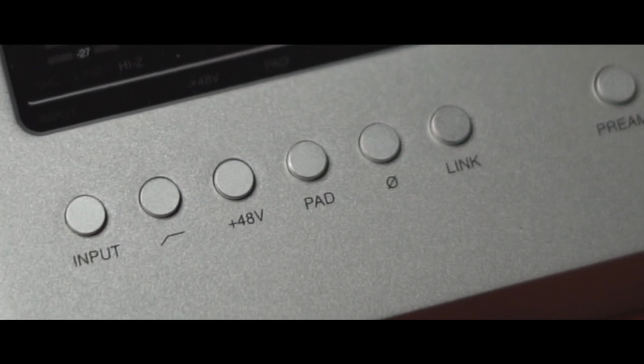Moving on, we have pad, and a pad stands for passive attenuation device. The way a pad works is that it simply reduces signal levels before the active amplification process on your preamp. And the reason that you'd use this is to avoid overloading on the signal. So if you have a singer that's really loud, right on the mic, that's a great way to make sure that the microphone capsule doesn't distort and send a distorted signal into your preamp to amplify.